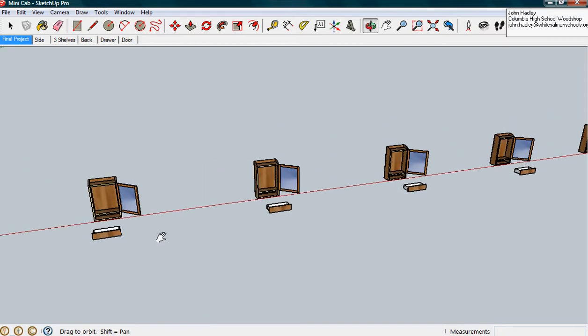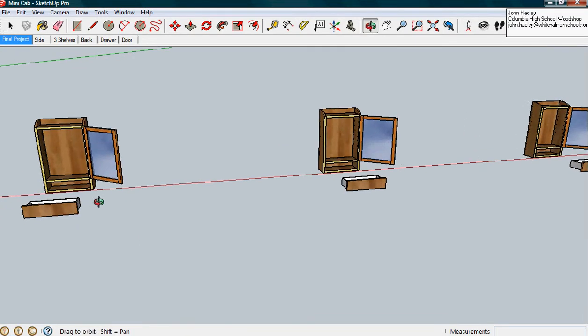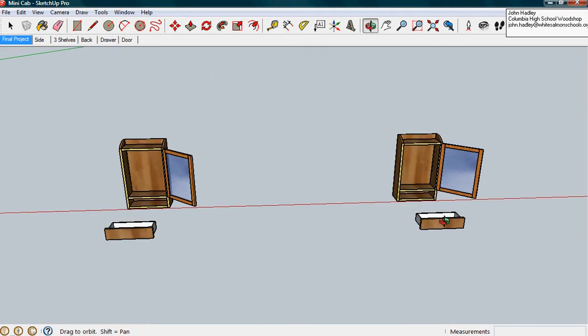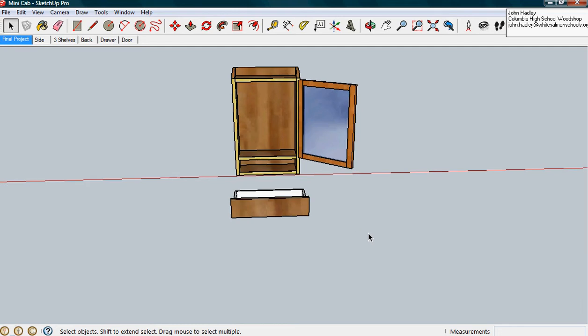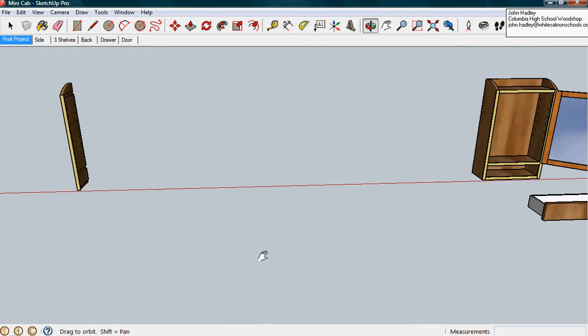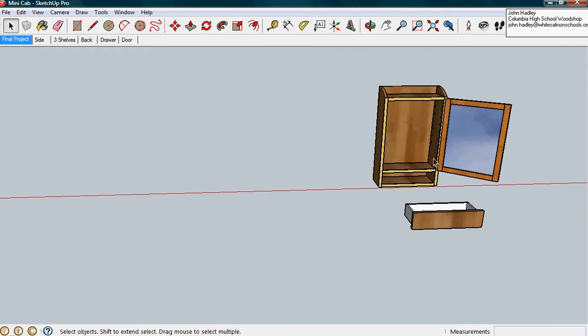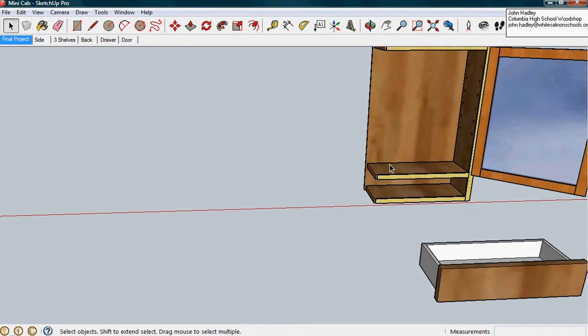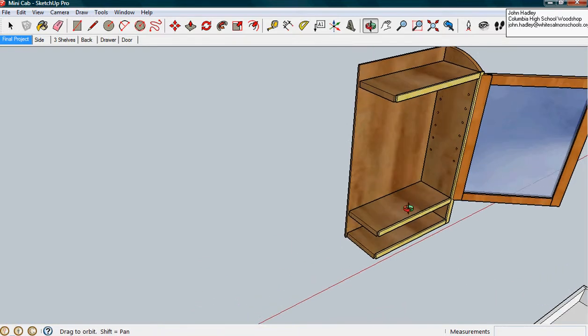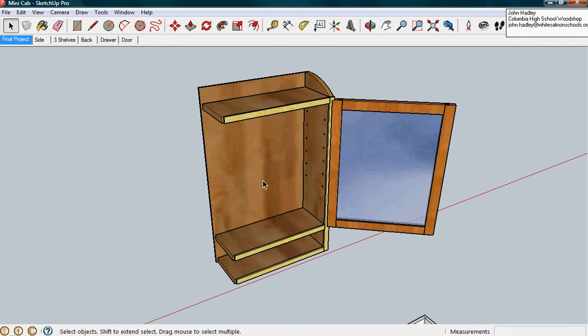out over this way. Okay, so at this point, what we're going to want to do is take these different pieces, and we're going to want to strip these different models down to just the different parts. So I'm going to select, remember, if I go from the right up to the left, I'll select everything that's within that group. I want a left side. I probably want to get then a side out of there, face frame out of there. I could expect that I might want to kind of go from a place like this, and that really shows quite a bit of details in there about the back.